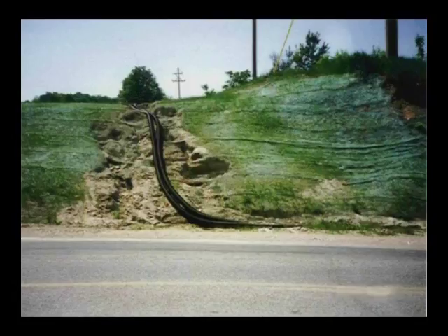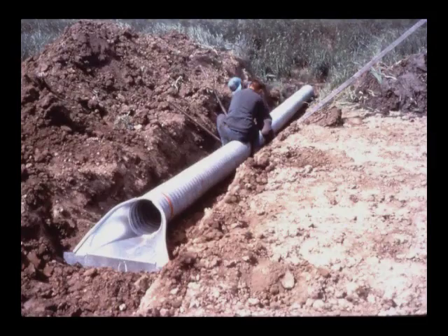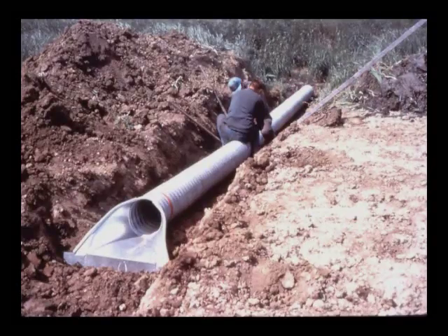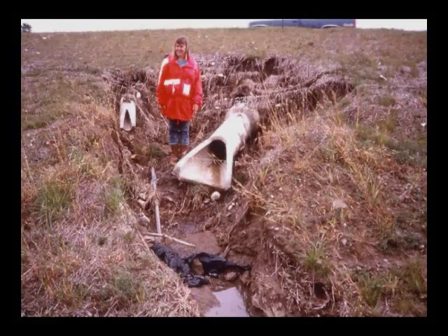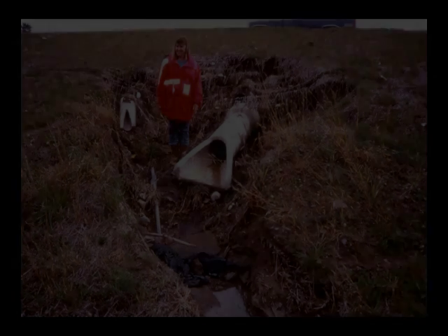Place large rocks on filter fabric downstream of the outlet, use flared end sections, or place large rocks or concrete blocks in the flume channel. The inspector will want to ensure that water is not flowing downslope in places other than through the structure, and examine the inlet and outlet of the structure for piping and erosion.